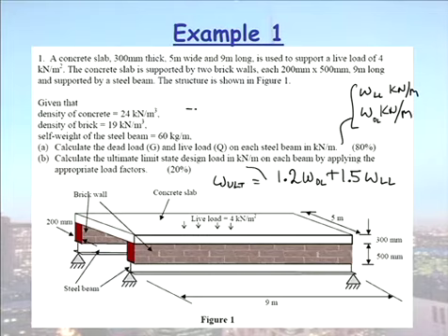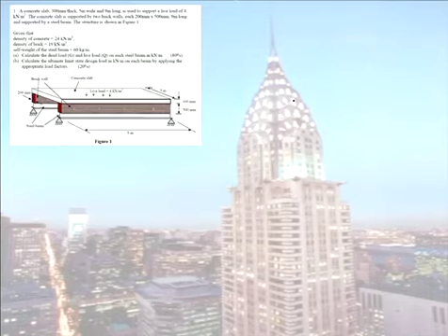That's on the basis that you now have a beam 9 metres long and it carries a load W ult. That is your starting point to check the stresses. Once you have your load on your beam, you can start working out what the bending stresses are on this beam because it's bending. So you have to turn your real life loading into an idealised number. So we clear where we're at now? Okay, let's get going.